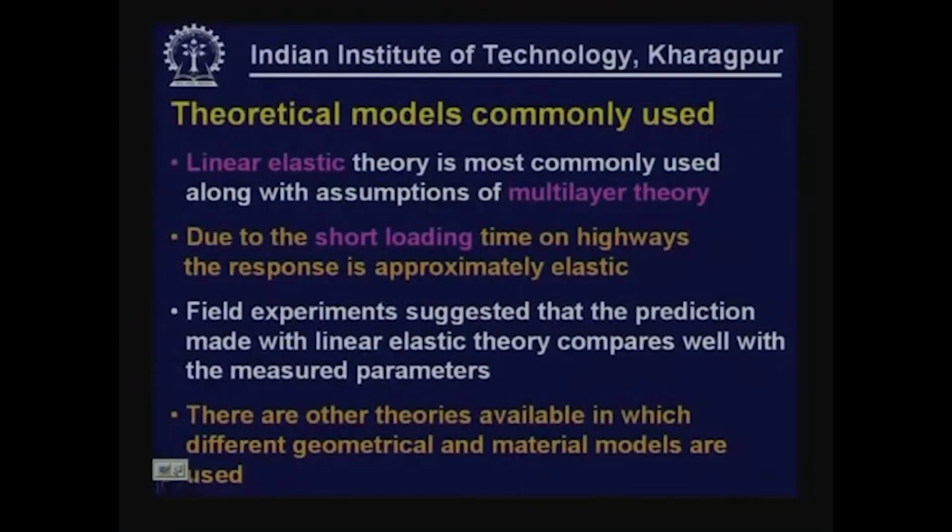So, this is the order of the duration of the load pulses. For such small load pulses, the behavior of the pavement is generally observed to be elastic. Most of the deformation is normally recovered, although there is some irrecoverable component of deformation. That is the reason why most agencies use linear elastic layered theory for analysis of flexible pavement.